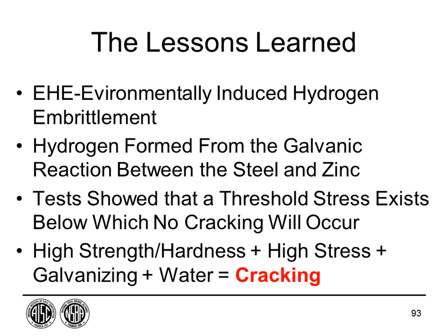One of the things to remember is high strength or hardness plus high stress plus galvanizing plus water can equal cracking. And so you should be very alert to this situation. Don't be tempted to just select a rod at a very high strength level and assume that it's going to work all right. You should be very careful about galvanizing these.